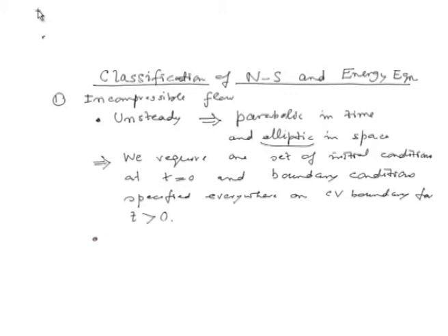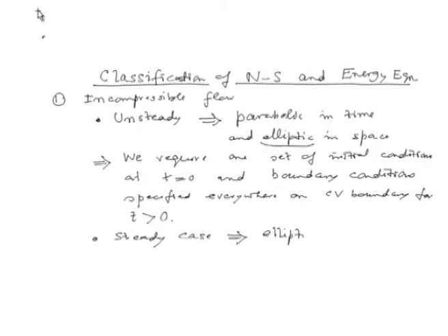For a steady case, the nature of both of these equations, Navier-Stokes as well as energy equation, is elliptic. So we only require BCs on the domain boundaries.